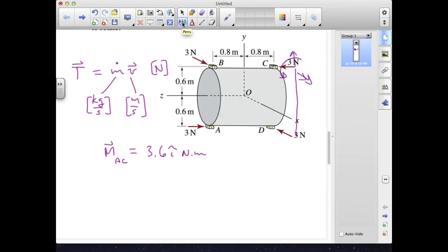The BD thruster pair also lies in the YZ plane, but these thrusters exert forces in the x direction. The perpendicular distance between these lines of action is also evident from the figure. The slope in the YZ plane forms a 3, 4, 5 triangle, and the distance between forces is 2 meters. The right-hand rule gives us the orientation of the moment from this force couple as having a positive y and a negative z component. It's a little bit difficult to see here because of the perspective view.